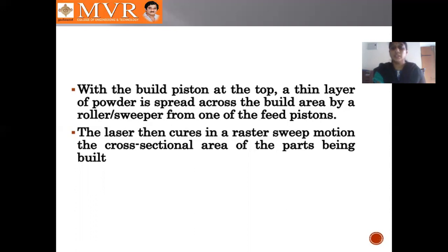Okay, in this powdered rapid prototyping system, the most important thing is that the powder should be very fine. Then only will the product appear neatly, and defects can also be easily detected. These powder-based materials give very high accuracy, along with strength, dimensional accuracy and surface finish.